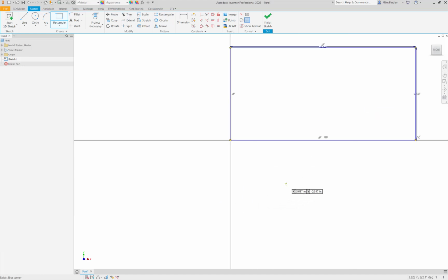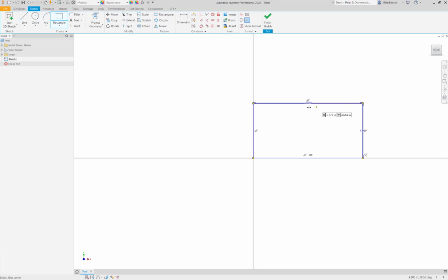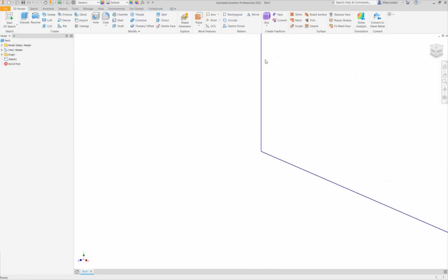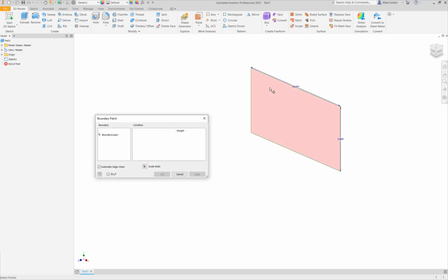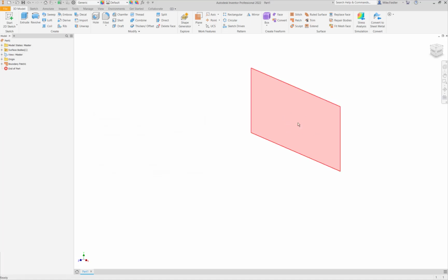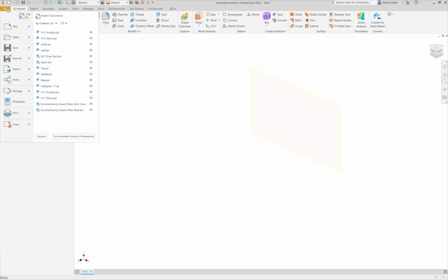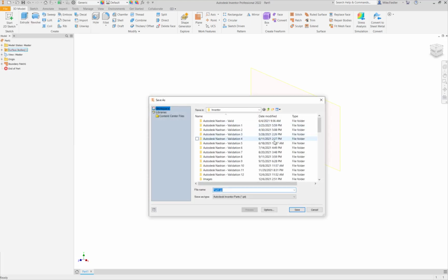We know from there, since we are using shells, or maybe you don't know yet, in order to get geometry that will be shells, all I have to do is patch that sketch region. So let's do that, and we'll say OK. Now that I have this surface model, when I take it into the Nastran environment, I can apply a mesh to it and make them shell elements. So let's go ahead and save this model. Let me do a file save here.